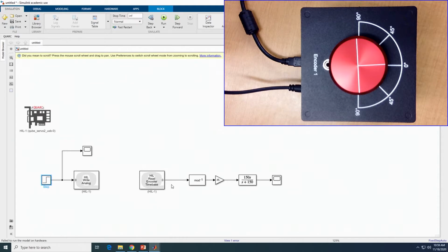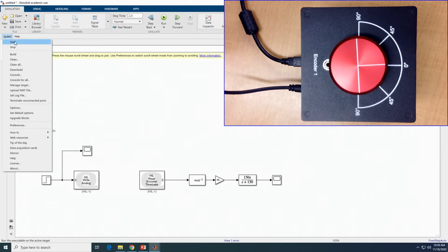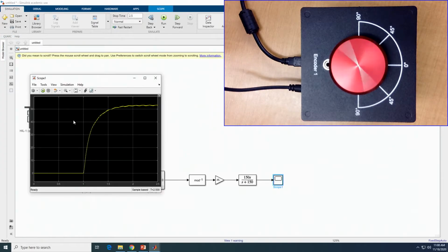And from the other end, we'll be reading the servo angular velocity in this scope. We'll use the speed readings then to estimate the parameters tau and k. The one more thing that I'm going to discuss is the simulation time, which I'm going to change to 2.5 seconds and hit run. So this is the velocity response to the step function for 2.5 seconds.